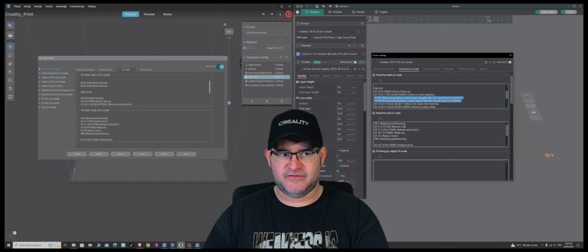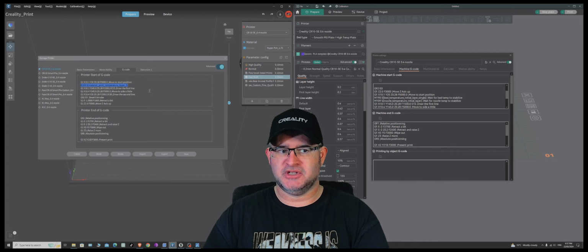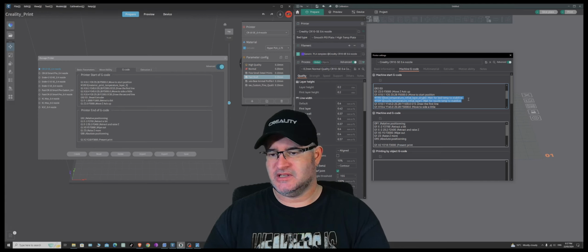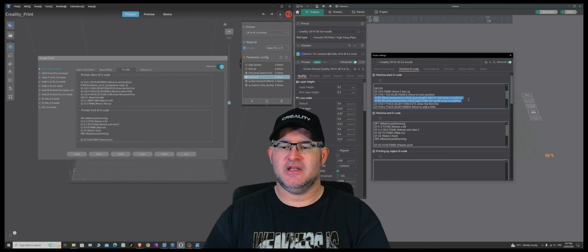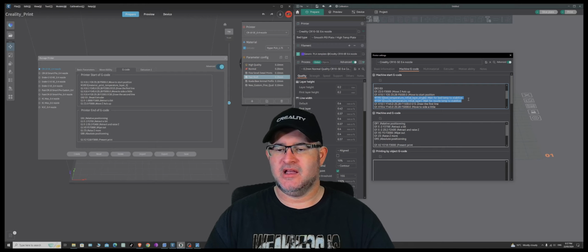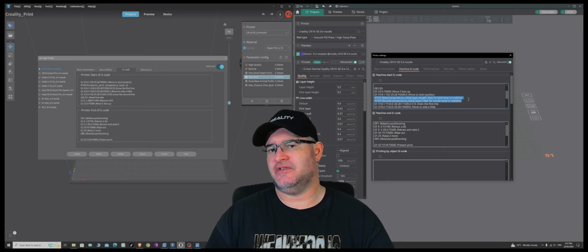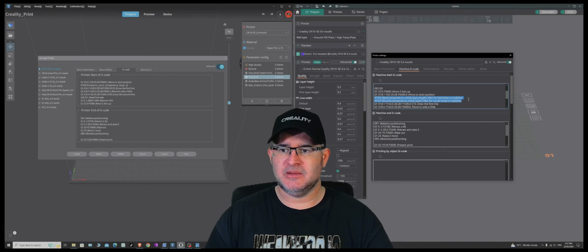As you can see from the difference between when we looked at the Creality Slicer over here, M109 material print temperature layer 0, whereas Orca Slicer has not only the M109, but also the M190. What's the difference? The difference is Orca recognizes that in the G-code, it wants to not only wait for the temperature to stabilize within the nozzle and the bed, but it also allows you to configure different types of bed sheets in the printer profile.